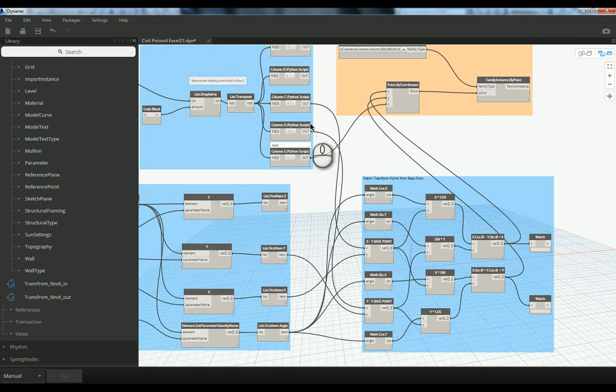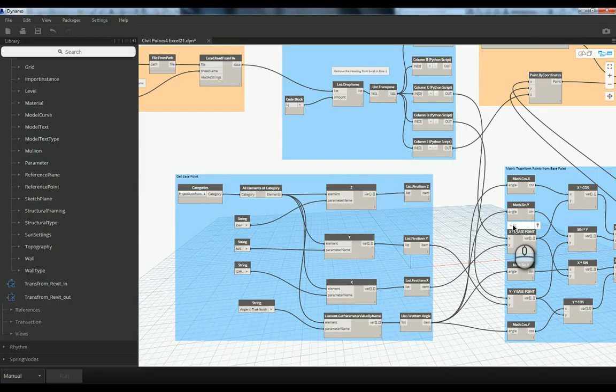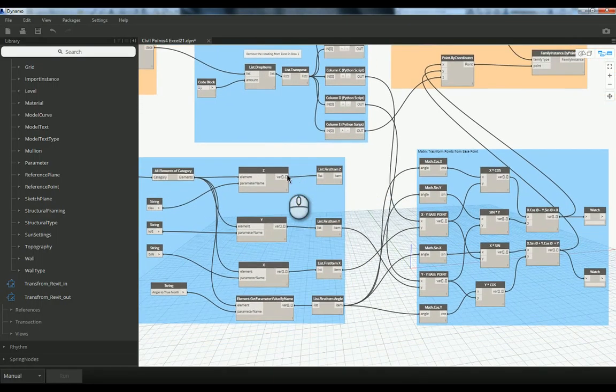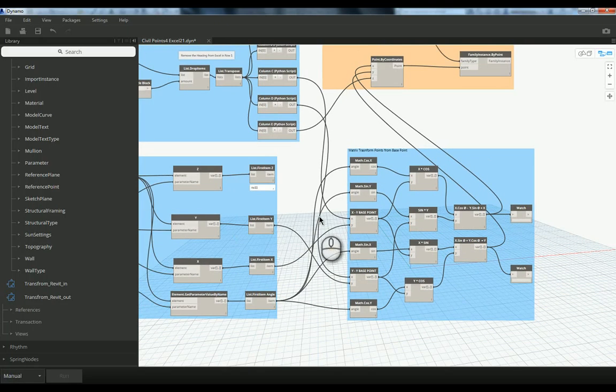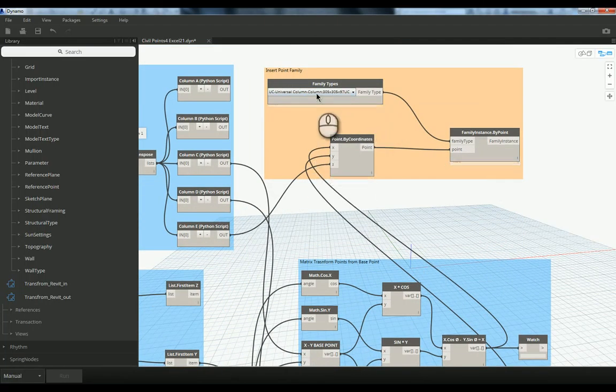And then each of them, so if we looked at C, comes through and drops down into the matrix transformation. So to transform anything into Revit, you basically need to do an adjustment because of anything greater than a 33-mile radius. So what I tend to do is first grab the base point. From that, take those values of the base point, and I put them through a matrix transformation that transforms the points I'm bringing in and the project base point and aligns it closer to the base point. And then the results of that, those points come in, and then whereby I can put families in.